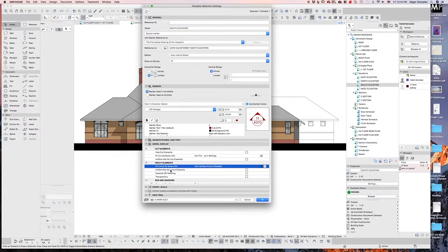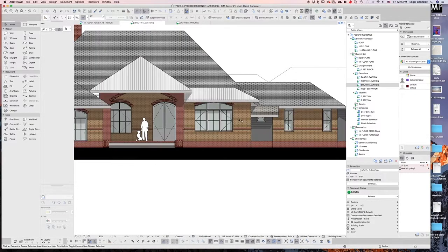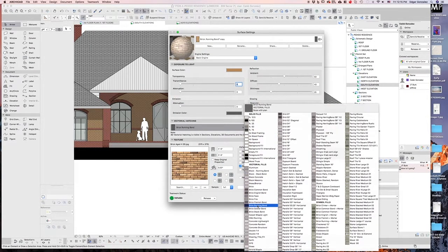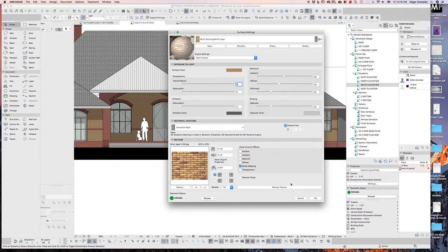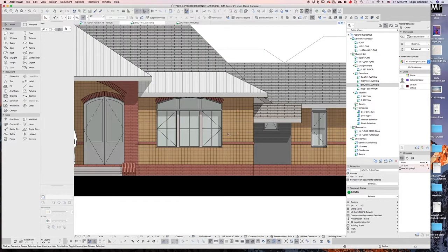We're going to turn on vectorial 3D hatching. That vectorial 3D hatching, what it does is it grabs the vectorial information from the material. I'm just going to change something here. I'm going to say this one is going to be, whatever, insulation rigid, right? So I change the material and that changes the representation, right?